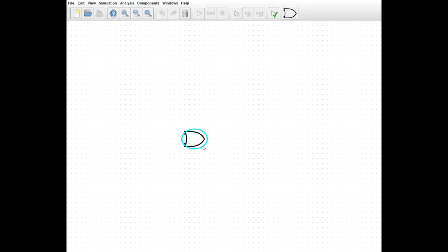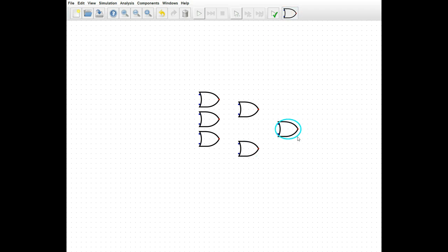The first thing that we're going to do is construct the basic circuit of how we're going to decode this, and we're going to use OR gates. So if we get an OR gate here, and we construct it as such. Well, let me actually drop this down just a bit. We are going to need a total of 6 OR gates per chip select signal.